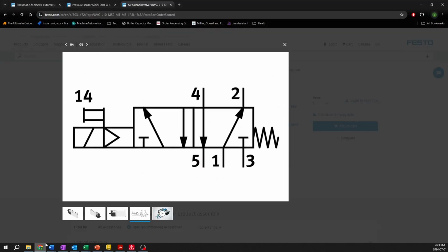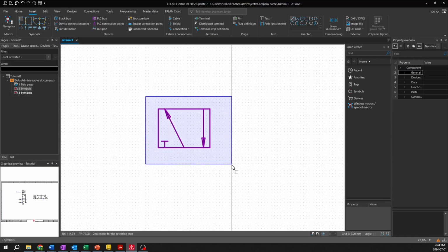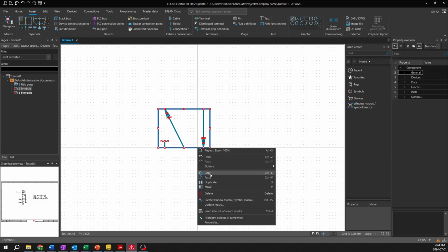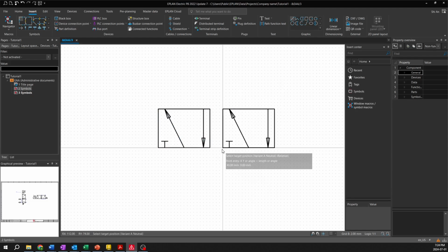For this valve, notice the valve body is symmetrical and we did half of the valve. That means we can just mirror what we just did to get the complete valve body done. Let's get back to our drawing board. Let's select, copy, and paste. And place it here.